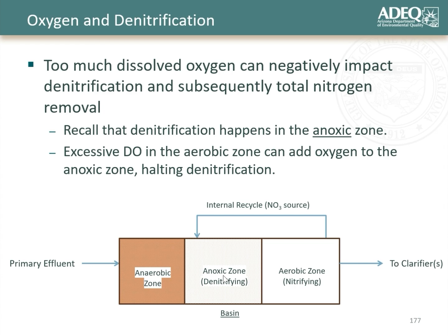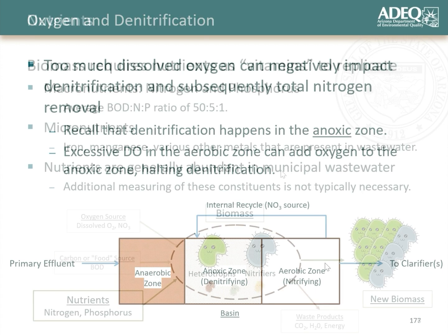So they would preferentially choose oxygen and leave the nitrate untreated. And so your denitrification would not occur. So making certain that you have not a high amount of dissolved oxygen, but 1 to 2 at the end of your aerobic zone is important if you happen to have a nitrogen removal system similar to this, to ensure that your nitrogen removal system works well.